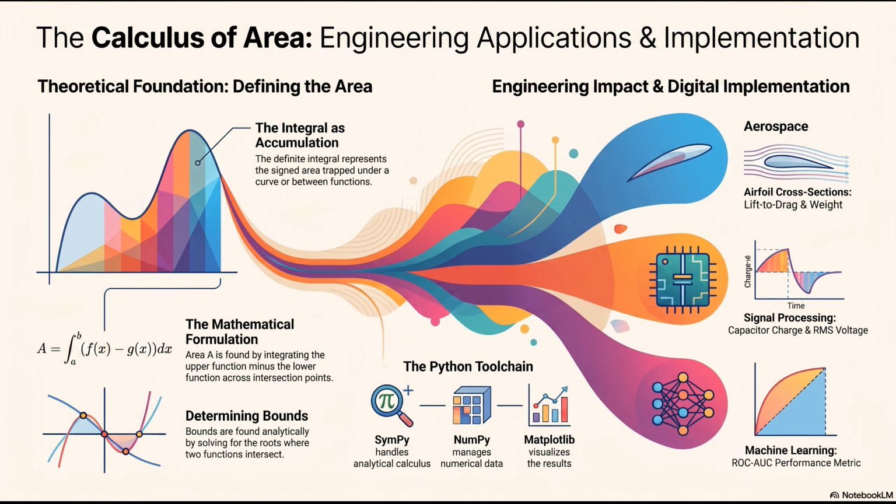And it isn't just the wings. The source document also brings up aerospace propulsion, the jet engines driving the whole system forward. The propulsion systems, yes. It mentions that the area under a pressure-volume thermodynamic curve equals the total work done in jet engine combustion cycles. Thermodynamics relies heavily on this logic. Engineers use a graph plotting pressure on the vertical axis and volume on the horizontal axis. Okay, pressure and volume. As a jet engine goes through its stages like intaking outside air, compressing it tightly, combusting the jet fuel, and then exhausting that high-speed gas, the changing relationship between pressure and volume traces a continuous loop on that graph.